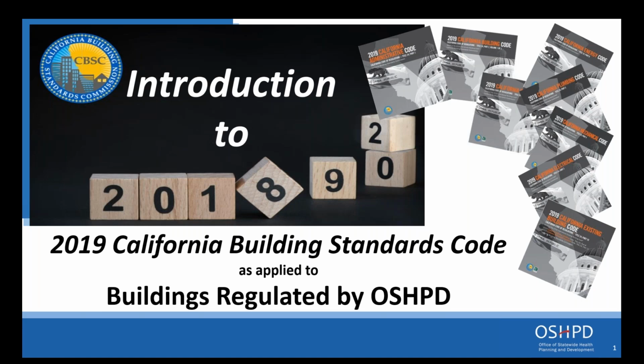Yeah, if I can follow up on that, Bill. The reason they put it in there is to encourage the development of such systems. And that's why we identified the requirements. If you did apply it, they would still have to meet the same requirements as a diesel generator, such as the 10-second startup time, things like that. So currently, as Bill mentioned, they do not meet that requirement, but if someone did come up with a system that did, they would be able to use it.